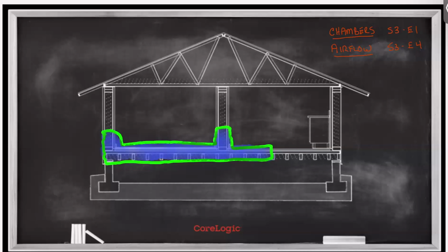And let me explain the reason behind that and then relate that back to how important that is to humidity control. The reason I know I'm going to need at least two is because I have to circulate all of the air within a drying chamber so that my warm, dry air can get to everything that's wet, and the evaporating moisture can be moved away from those wet materials and can be managed through my humidity control system. Well, that would be a really bad idea between the air down here, where I have a bunch of wet surfaces in my crawl space, versus the air up here in my living space, right? These two air masses should not be exchanged with one another. There should not be circulation between the two.